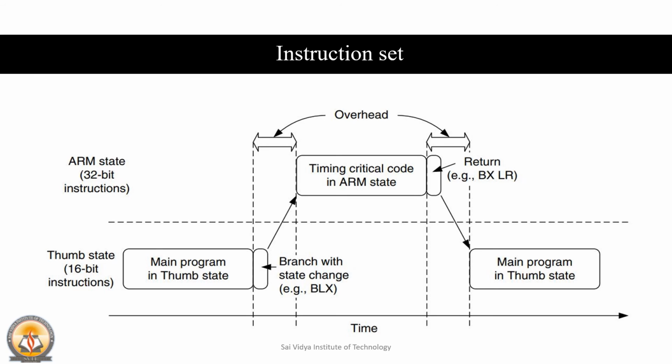The Cortex-M3 processor has a number of advantages over the traditional ARM processors, such as no state switching overhead, saving both the execution time and the instruction space. No need to separate the ARM code and the Thumb code source files, making the software development and maintenance easier. It's easier to get the best efficiency and performance, in turn making it easier to write software because there is no need to worry about switching codes between the ARM and the Thumb to try to get the best code density as well as the performance.